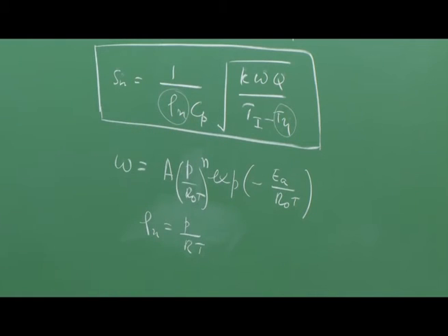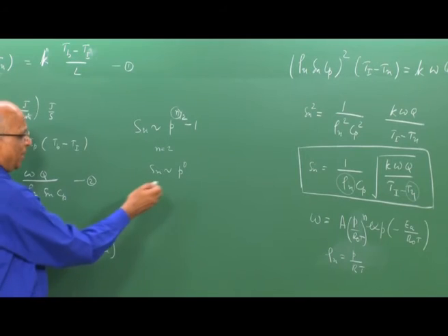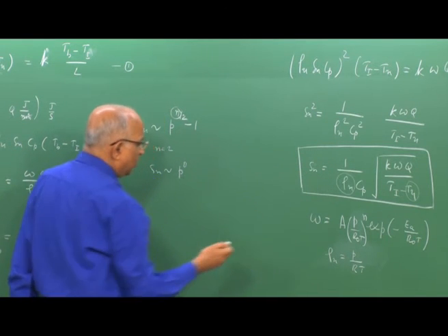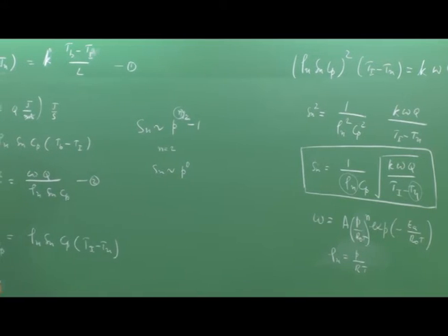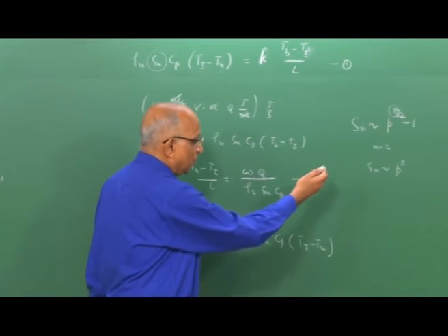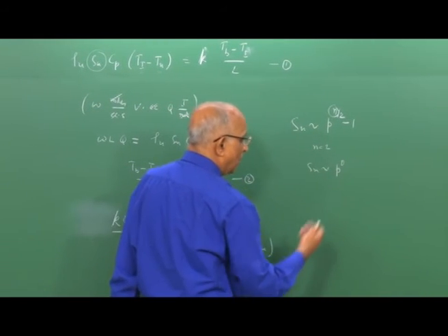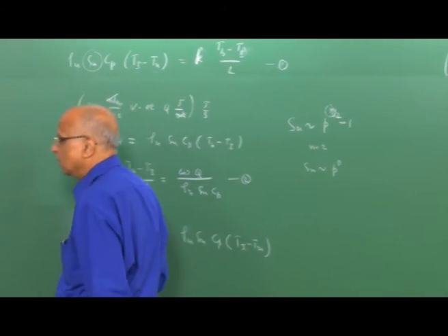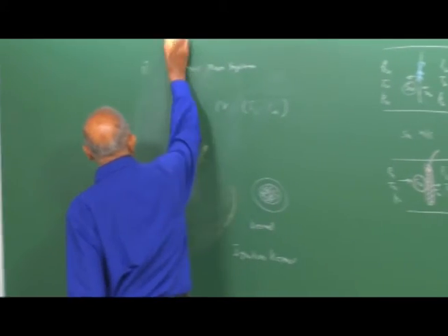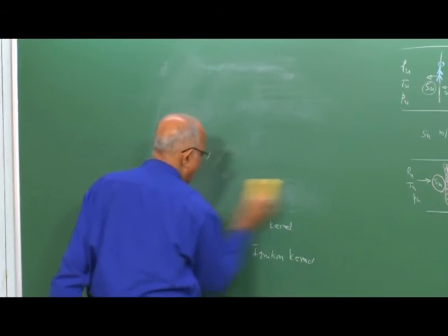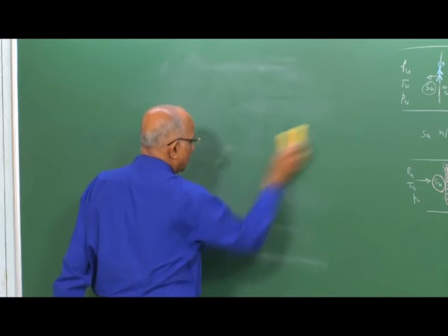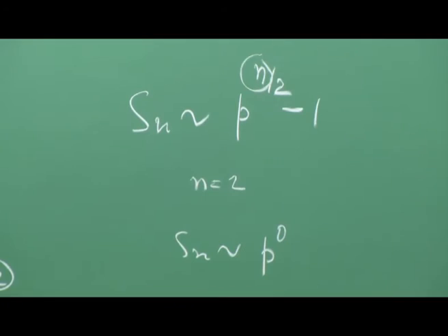We have these particular relations, and therefore let us try to get some feel for the speed. Is it 1 meter per second? Is it 100 meters per second? To be able to do that, let's put the values down, or people have put the values down, and let's see what values of the flame speeds we get. I quickly go through a few cases, maybe 2 or 3 gases, and let's try to get a feel for the speed with which the combustion moves into the unburnt gases.